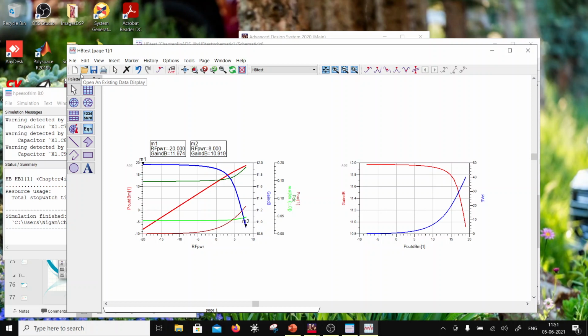You cannot just increase the size of the FET and say that, oh, I'm maintaining the same quiescent current and I'm going to get the power go up. This happens in an HBT, not in a FET. So this you should know when you are a designer for PA.